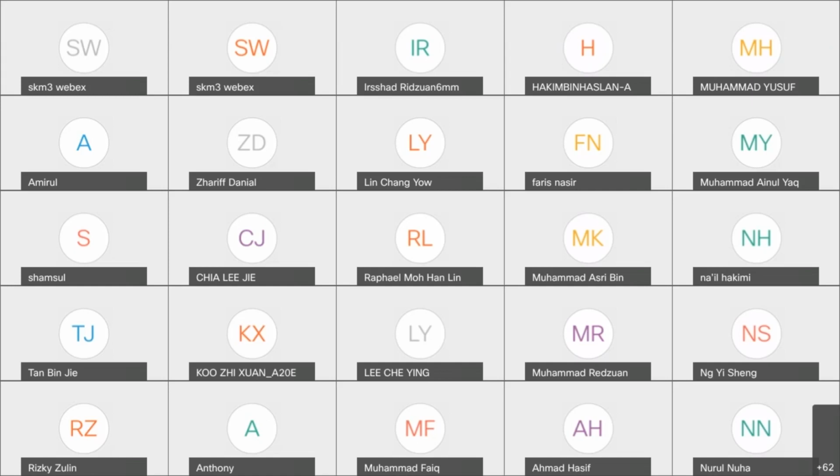After you get the shear stress tau 1, tau equal to viscosity du, or tau equal to mu over u over y. You put in the values, you get tau 1 and tau 2. From tau 1 and tau 2, you need to convert into force. So force equal to tau multiply with area. So tau 1 multiply with area, which is 4 feet, and then you get force 1 and force 2. The total force must be the combination of the top force and the bottom force, which is force 1 plus force 2. Finally, the answer is 0.463. That is the final answer.